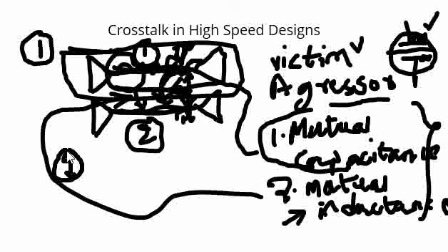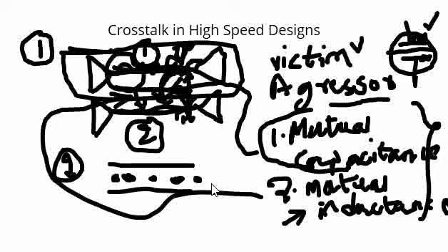One of the hardest ways of doing it is, in between two traces, to stitch ground wires to the ground plane such that there isn't any coupling happening. This cage that we form, these wires that we add, can be done only in boards where you have that much space, which is not the case in the high-density boards we are talking about, right? So this is a non-practical thing. But if there are traces which are isolated away from other things and there is enough space, we can do this as well.